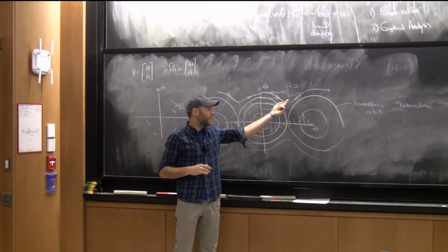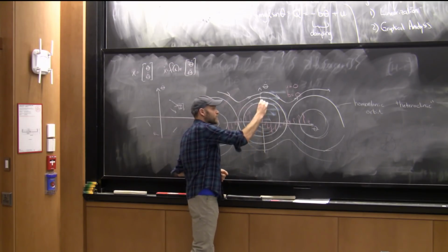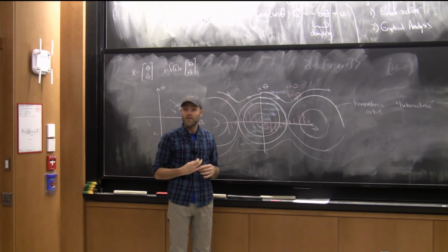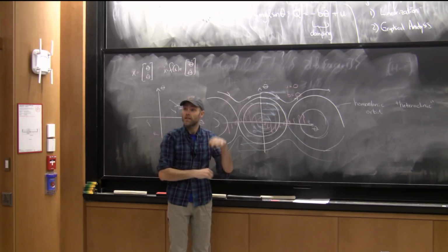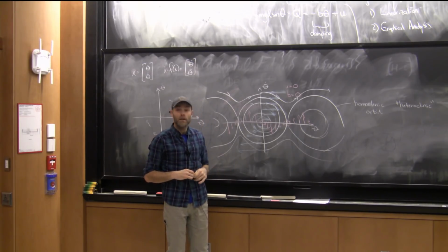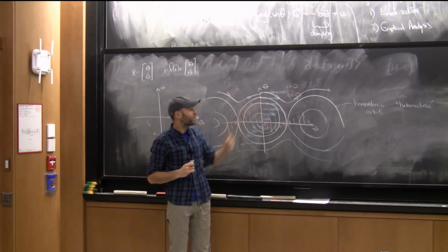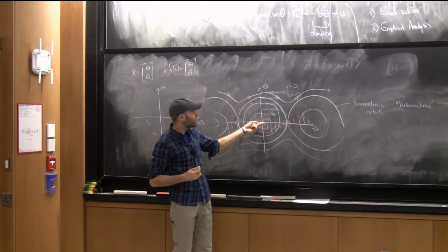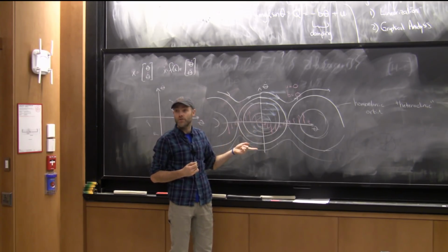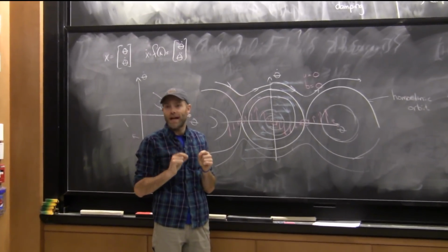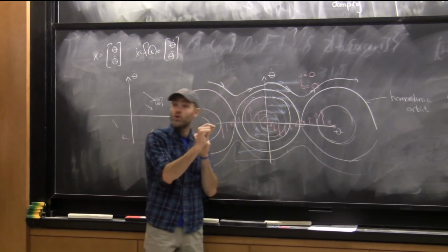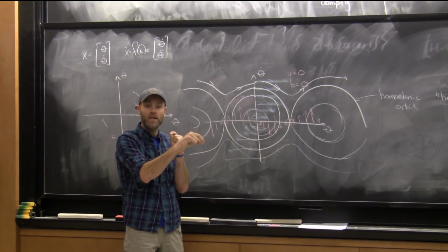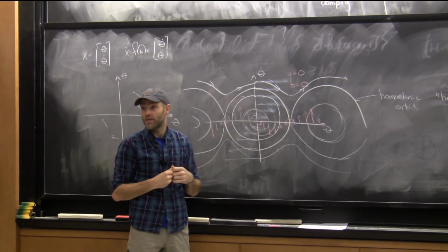Okay, once I add damping back in, if I take B and drive it above 0, then my trajectories are going to converge in a spiral down to the fixed point, and I've regained asymptotic stability and, in fact, exponential stability in these cases. Okay? All right. In fact, let's think about what happens if you have u not equal to 0 in these equations. We know that there's 2 components to every one of these vectors I drew. The x component is just theta dot. So nothing I do with u is going to change that. If I put torque in, it's going to change my acceleration, but it can't change the x component of this.